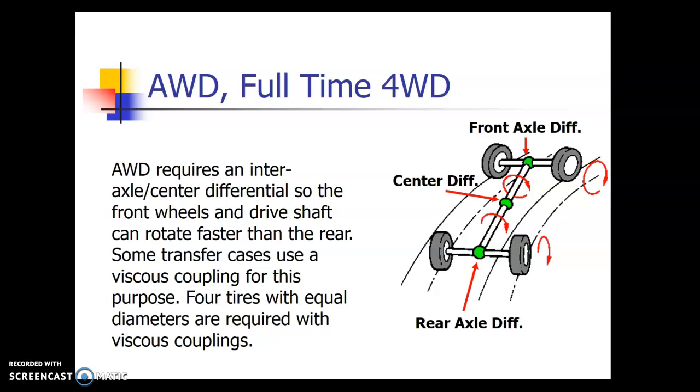If you're cruising down in the snow, I would not want a locked rear end. That locked rear end can actually shift the whole axle to the left or to the right based on slope or pitch of the road, crown of the road. And again, maybe I want to lock front to rear axles because I'm trying to crawl out of a rock spot.